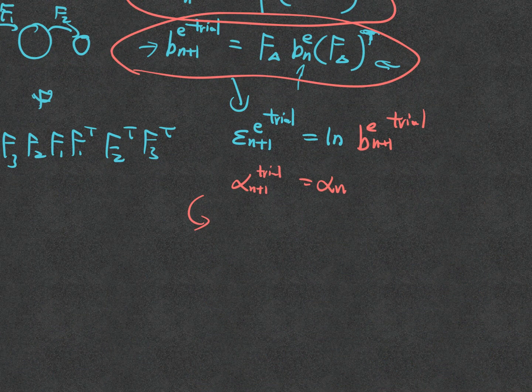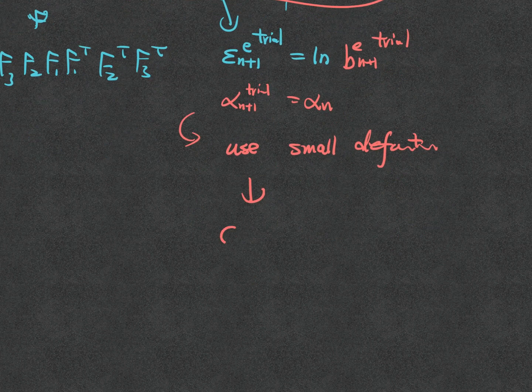So I would then use the small deformation algorithm. And after that, I just need to compute sigma_{n+1} equals the determinant of F_{n+1} to the power of minus 1 times tau, and that's it. So from that constitutive law, I get the Kirchhoff stress, and I apply the Jacobian. I can get back the Cauchy stress if I want to. So that's a trick. This is like magic.